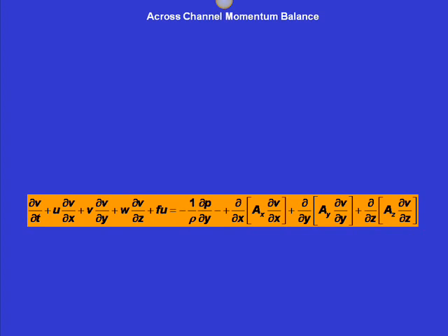Oh, right. Because we said that the friction can be, in the case of rivers, in which the flow is unidirectional, driven by a sea level slope, not by a density gradient only. It's a homogeneous situation. And the other situation of pressure gradient being balanced by friction is that of estuaries, right? Where we have the pressure gradient driven by slopes, but also by density gradients, and balanced by frictional effects, right?